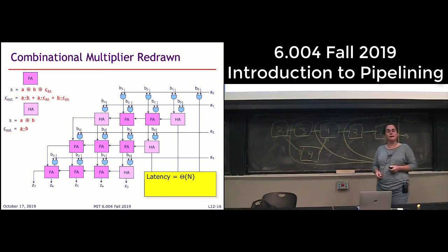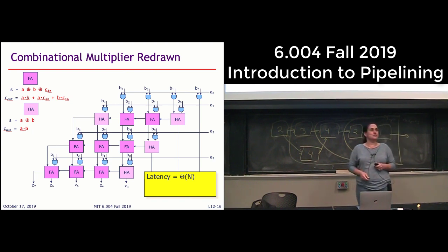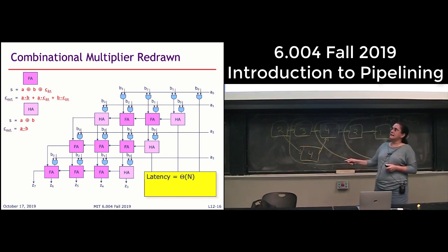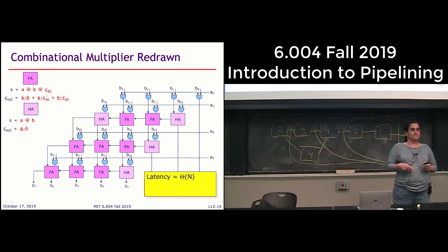before this set of adders begins to work, okay? And so if I think about what my propagation delay of this is, it's basically proportional to the number of bits of B, which is n, and then I basically have 2 more full adders that I have to go through for every additional row, okay? And so given that I'm only adding another constant for every row here, I'm ending up with something that's of order approximately 3n, but it's still not n squared, okay?